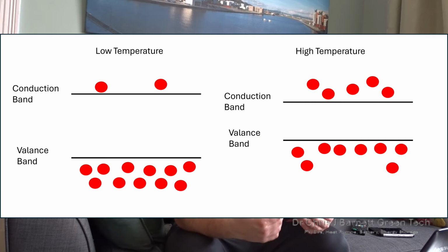Because there's a number of ways of looking at this. Some people will explain this as the band gap of a semiconductor effectively getting smaller when the heat goes up. Or it can be thought about as electrons in the valence band being promoted up to the conduction band more easily because they can take on that heat. It's a bit like applying a voltage. And what this means is that you can get current flowing in your solar cells more easily because you promote more carriers. And this is something you don't particularly want inside the solar cell when it's generating electricity.